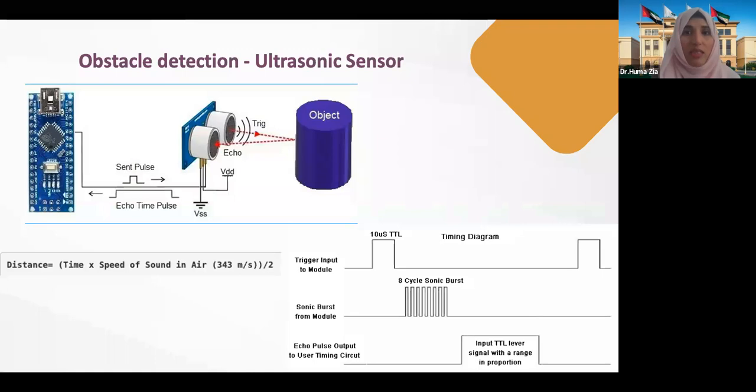What this ultrasonic sensor does is that it emits ultrasonic waves, sound waves, and those sound waves hit an obstacle and return back. And the distance is actually measured. How much distance that is, by the simple S equals V times T formula.